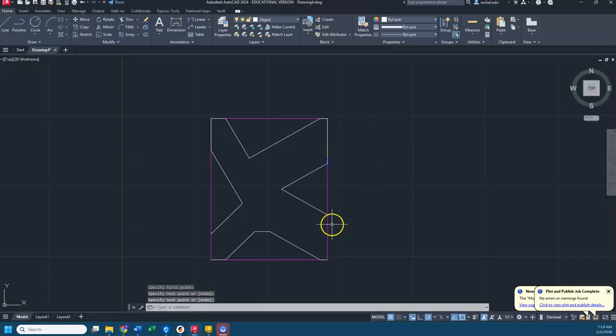But turning off a construction layer can be helpful. I don't need to delete the construction layer because it's not going to print. So I'm going to come to layout 1, and it can actually help dimension a little bit when we're grabbing those angles.